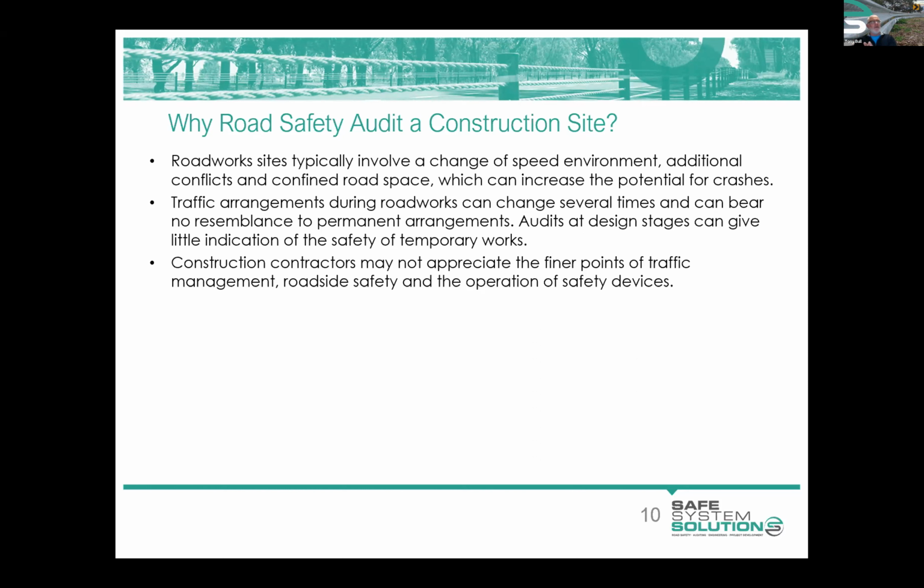And that's why you can't really do a road safety audit on your own project, because you can sometimes have blinkers on. And that's why a road safety audit is such a powerful tool. You've got an independent set of eyes looking at the project in its entirety to make sure that it's operating safely for all those on that site, whether it be the travelling public, pedestrians, or the workers and the use of their machinery on that site. As I said, it's a really powerful tool.